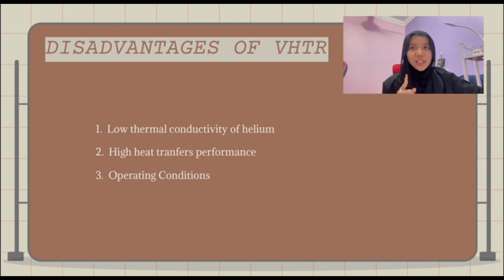Lastly, operating condition. The operating conditions of the VHTR are beyond the temperature and irradiation conditions of current light water reactors. High temperature will increase the rate of chemical reaction with atomic diffusion events on the surface of the metal in the VHTR.